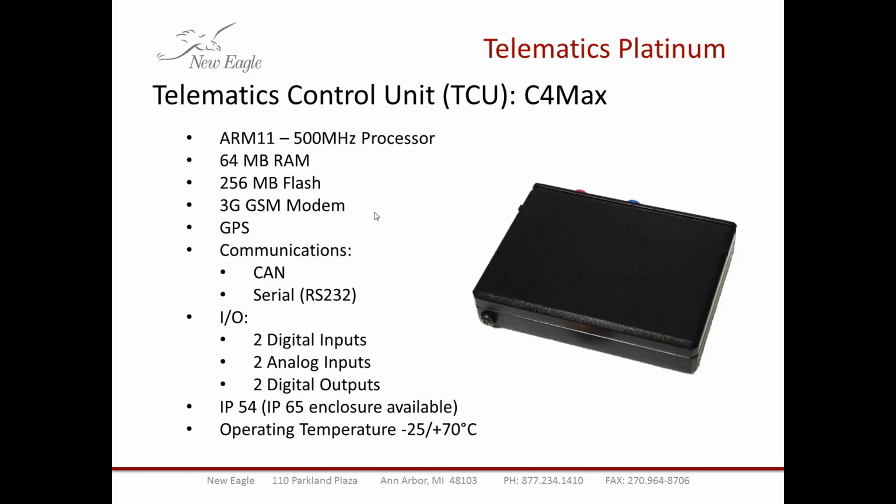The C4MAX box is IP54, and we have an IP65 enclosure that's available. The operating temperature listed there is -25 to +70 C. We have seen it operate at lower temperatures than -25, but the rating is at -25 because it does have an internal lithium-ion battery that does not charge colder than -25.